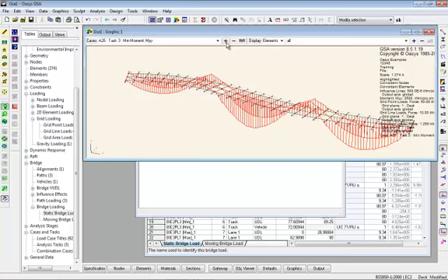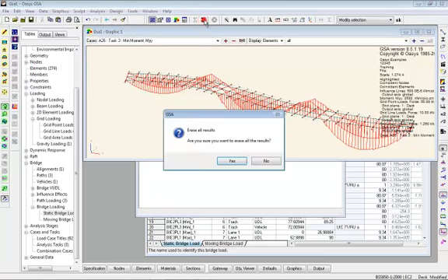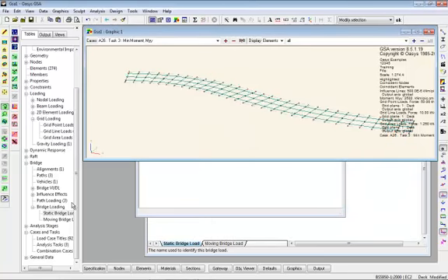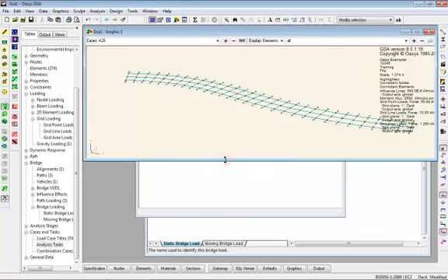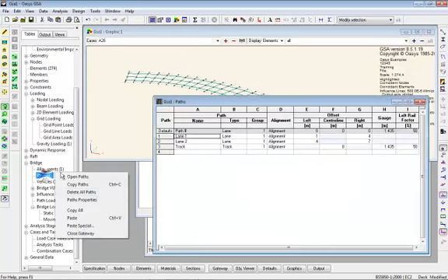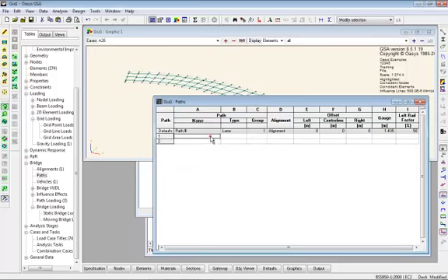And if you want to make it really easy, if you've got just a highway load, delete out all those analysis tasks because we can't have more than one bridge case. And I'm going to delete those paths, and I'm just going to create a carriageway on here which goes from 1 over to 7.